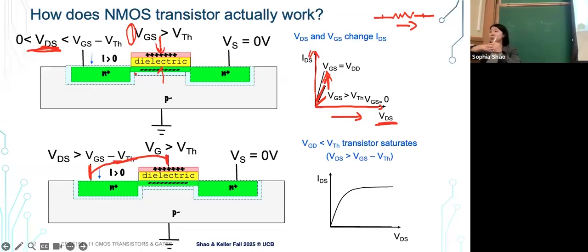What if the other two terminals are so close? Have people heard of the pinch-off region for semiconductors? Ryan, what does that mean? You get less current. Right, so why does it saturate at that point?